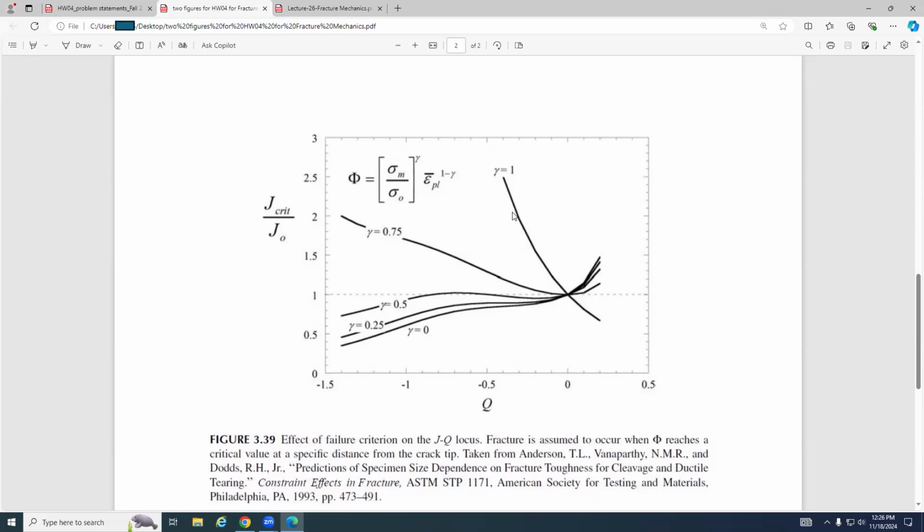So under what circumstances should we do this? Before we do anything, okay? Suppose this is a new material. We use a new material and do some experiments, and at the very beginning we assume small scale yielding, right? Because it's totally new for us, we have no idea. Then we can just use this to check whether the single parameter assumption is good or not. And how to do that? First, you test under what condition this fails. Is it correct? And under what condition does it fail?